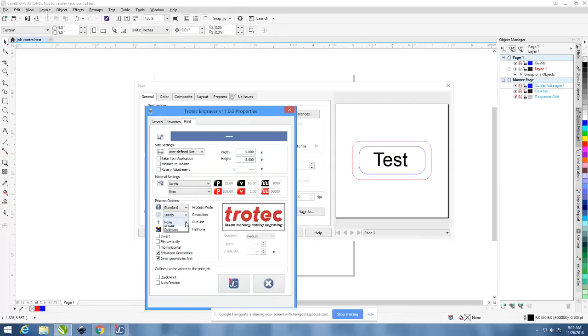So moving on here, we have our cut line. This is pretty nifty. If you hadn't made a cut mark in your design file, you could come here and use this to cut out the design that you're using. This is great if you're making ID tags with our materials here. If you select none, obviously nothing's going to get cut. Rectangular here will cut a perfect rectangle around your design. And then as we move through here, you'll see it'll try to make the best shape using curves to cut a curved line around your design. And using optimize, it'll come in here and cut perfectly around all of these shapes that you have here.